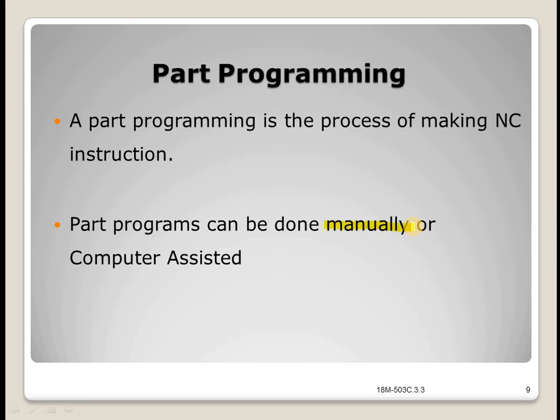It also includes other data such as preparatory commands, miscellaneous instructions, and speed and feed specifications, all of which are needed to operate the machine under tape control. The manuscript is designed so that the NC tape can be typed directly from it on a Flexowriter or similar tape punch device.